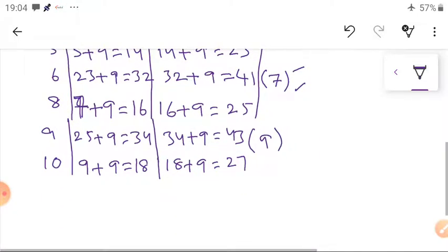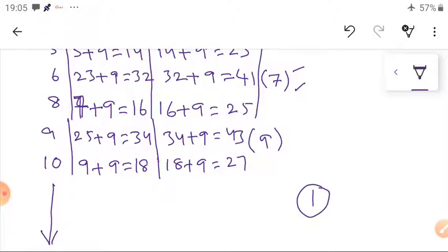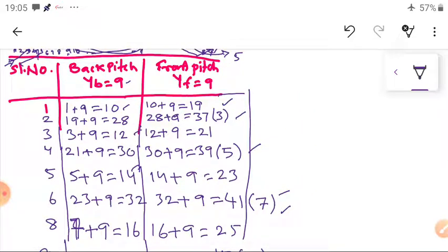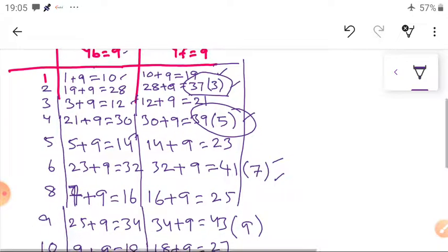Similarly you complete the total diagram until you get the first conductor, 1. So dear students, this is a simple diagram, simple addition. In lap winding there is a plus and a minus, but in this case both are plus values. But you have to keep in mind that whenever the value goes above our maximum number of conductors, you have to make an arrangement here. So this is a simple technique. Let us complete this total table. Similarly you complete it.